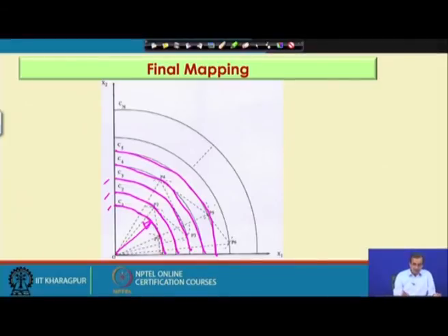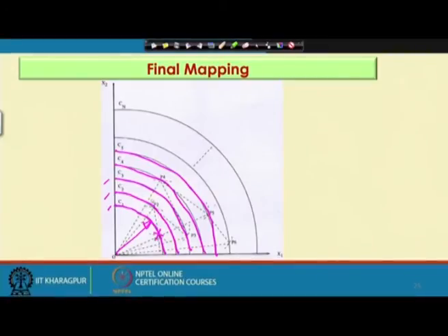And now, on the first circular arc, we can select any point at random. Let me select this particular point, and once I have selected it, I also know the Euclidean distance between the closest connecting weight and the next closest connecting weight. Considering that numerical value, I draw one circular arc on the second circular arc, and I will get one intersection point, that is P2.